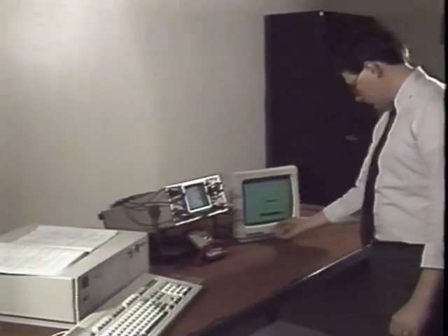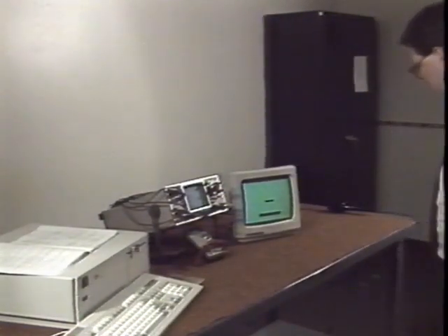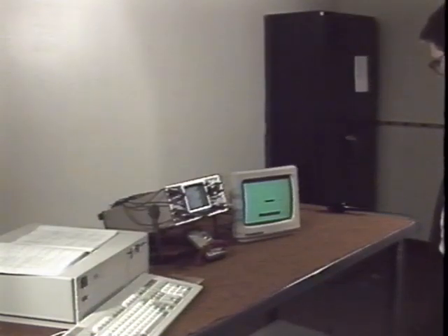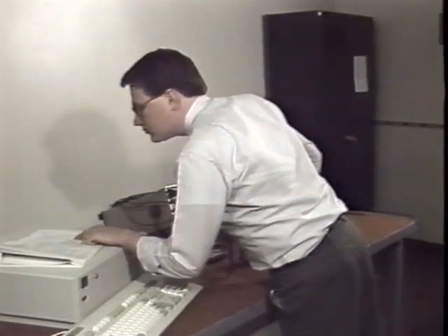As we discussed before, we will adjust the power supply voltage first, since it affects the operation of the rest of the monitor's circuitry. Select a program option that will produce a full bright screen and rotate the brightness and contrast controls to obtain the brightest possible pattern. These two steps produce maximum current draw so that we can adjust the power supply under maximum load. Connect a voltmeter to the test point specified in the manual.